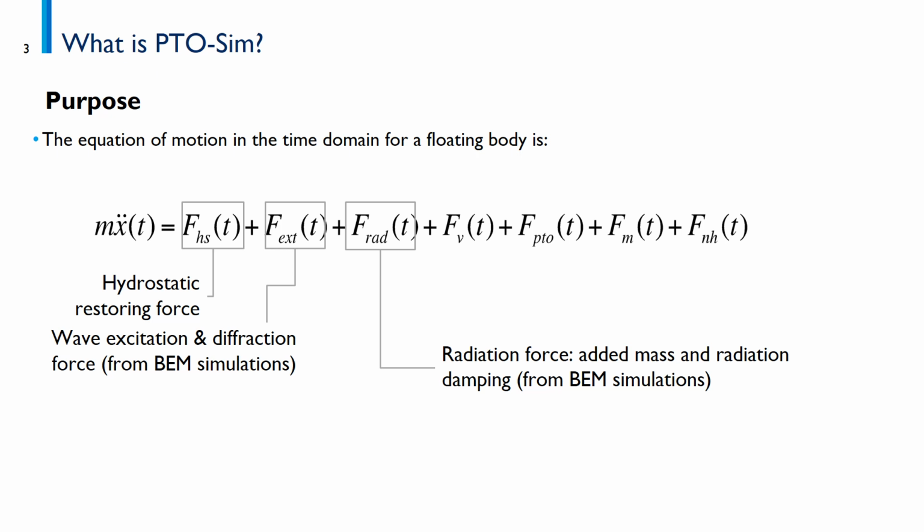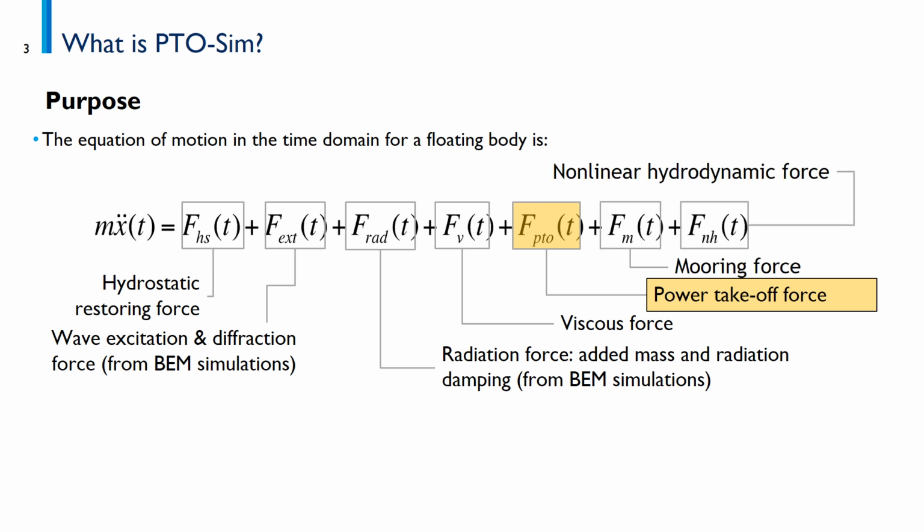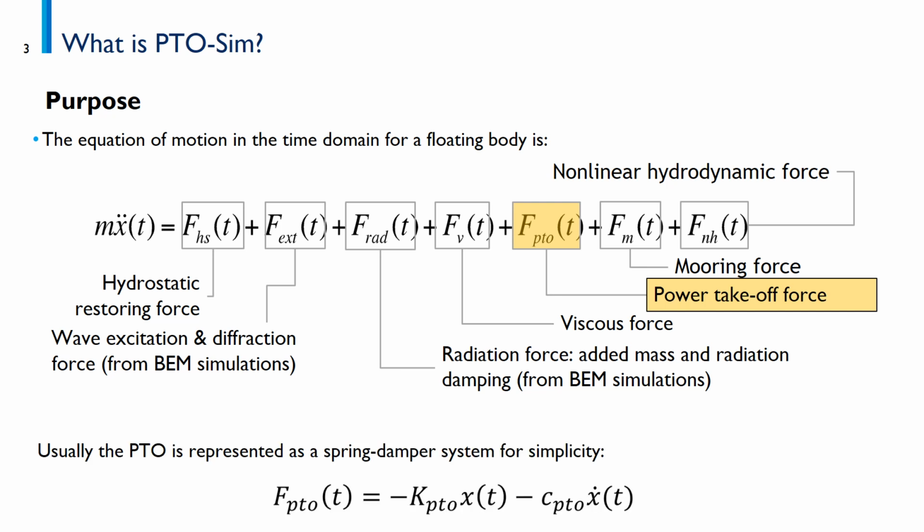That force is also calculated based on the boundary element method simulations. We have a viscous force, a power takeoff force, mooring force, and the nonlinear hydrodynamic force. So the purpose of PTO Sim is to calculate the power takeoff force in this equation.